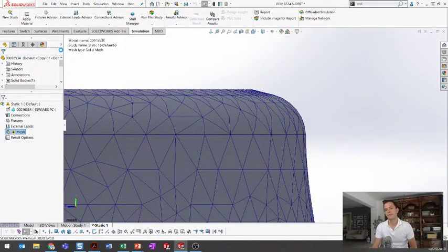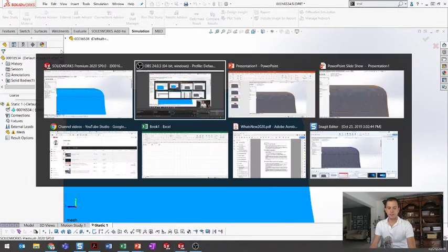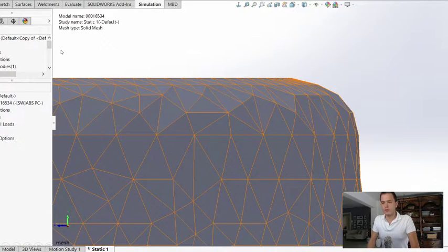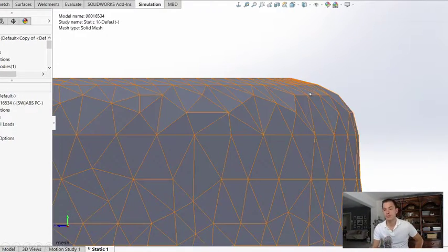All right. So I'm going to set this off here to mesh, and what I want to do is switch over to what I have here, right? I have draft quality, high quality. I'll switch back and forth, and I want you to pay attention to this filleted area here, right? Look at how nicely this high quality, because it's blue, draft quality is orange. You can see how it's really jagged and kind of sharper and really segmented.